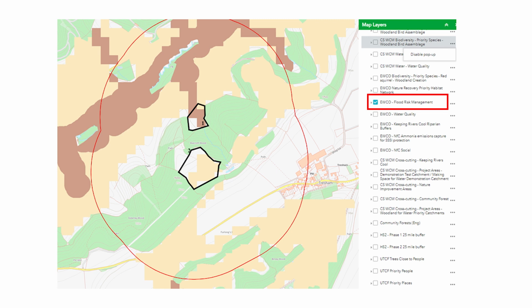The next additional contribution we're going to look at is flood risk management. This additional contribution is available where areas of appropriately designed new woodland in the right location can help reduce the risk of flooding by slowing flood flows and increasing the retention and infiltration of water on the land by creating woodland in the wider catchment area, riparian woodland, creating woodlands along watercourses, floodplain woodland, and cross-slope woodland, where creating small areas of woodland such as shelter belts can reduce rapid runoff from higher land.